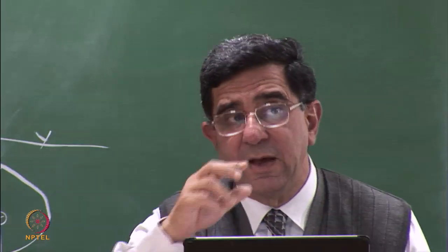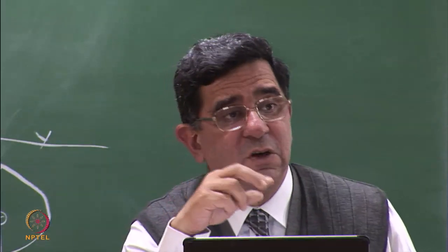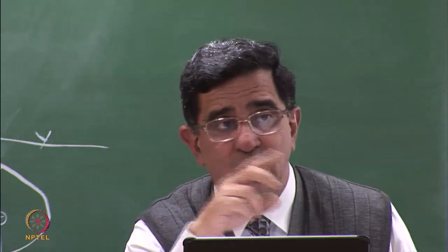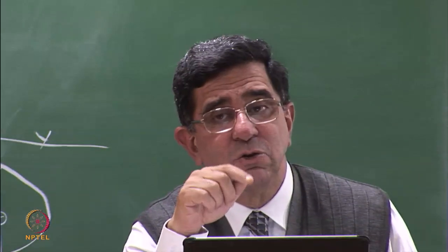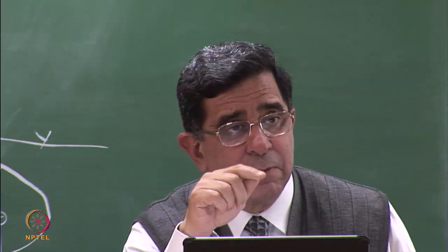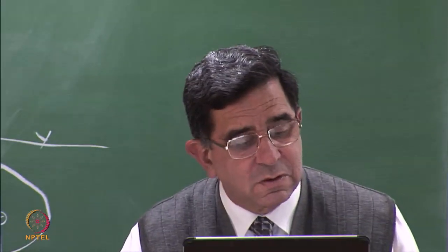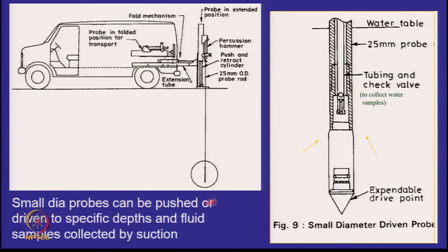You are not bothered here about whether you are destroying the structure of the soil, whether the strength has changed, whether you are getting an undisturbed sample. No. What are you bothered about? You would be able to reach a particular depth and pick up the liquid sample or the gaseous sample by suction. So for small depths, we have special probes which can be pushed or driven into the ground to collect the samples by suction. So both these devices which I have talked about, the small dia probes